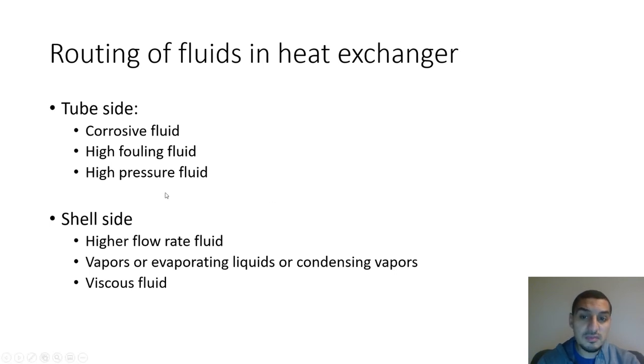Again, the same for the high pressure fluid. High pressure fluid requires thick tubes and a thick shell, and that's why you would prefer to put it in the tubes, so that we can use only tubes with higher thickness, which is not going to be very high thickness, by the way, compared to the increase in the thickness of the shell because of the high diameter.